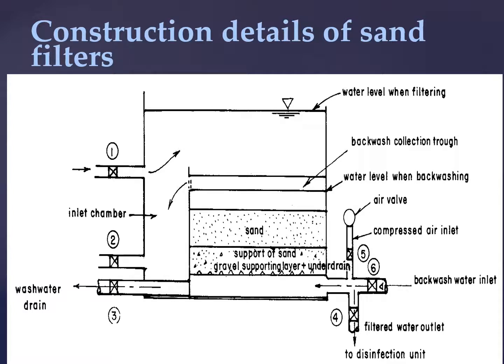Construction details of the sand filter. Here is a profile of the filter. Number one is the inlet, water enters, and then at top you have sand, and at the bottom you have gravel or support for the sand. Gravel is not media. Gravel is just support for sand. Our media here is a single media, that is sand. You put water from the top and you filter it, and from the right you take water at number 4 as the filtered water outlet. Then you send water to the disinfection unit.